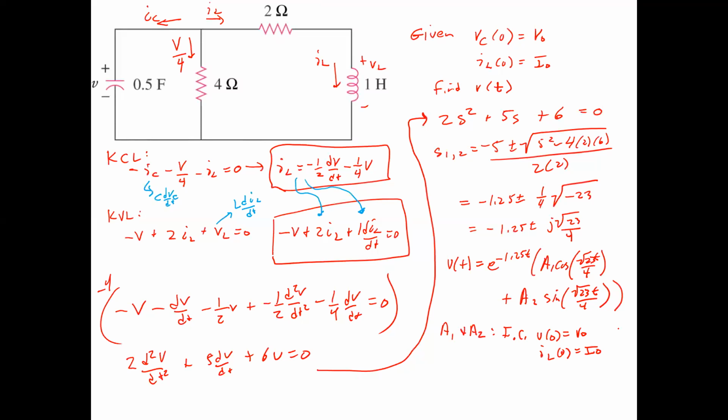we're going to have to find dV dt at t equals 0. Well, we have 9 minutes. Why don't you try doing that? That's such a good, challenging thing. Why don't you just try doing that right now? dV dt at t equals 0, which is IC of 0 over C. Try to reason your way through that and see if we can come to an agreement. You're going to want to redraw the circuit where the initial values are applied to the capacitor and the inductor.